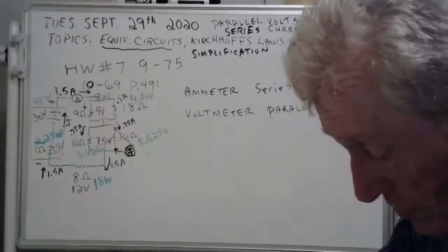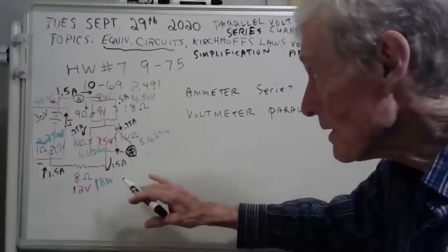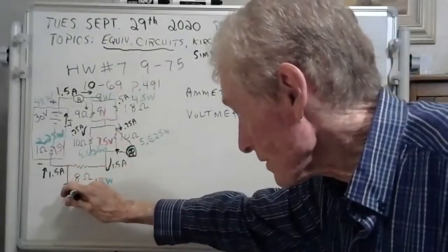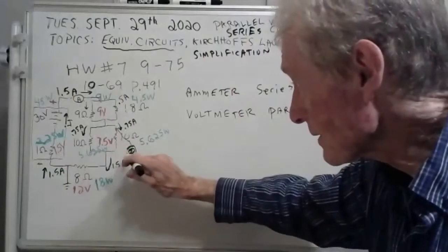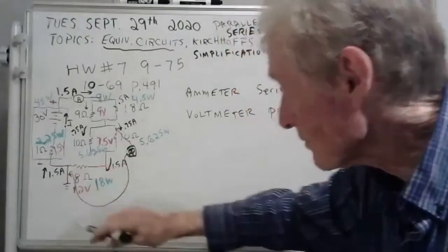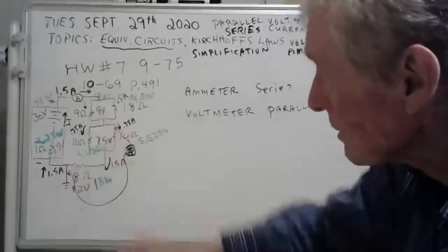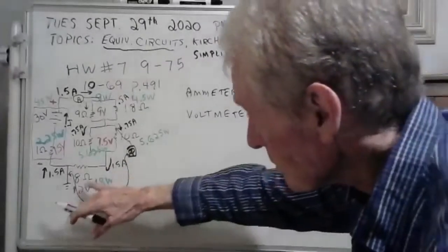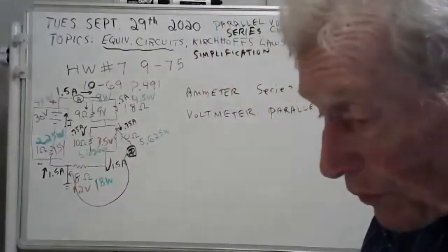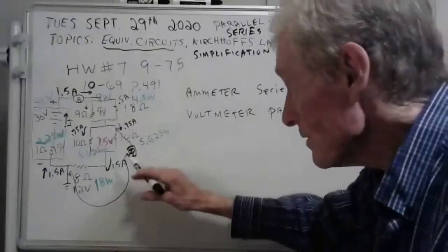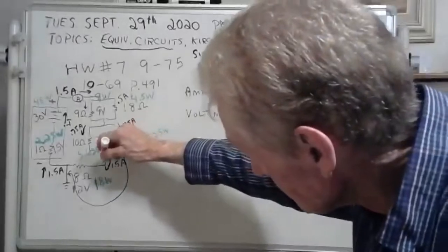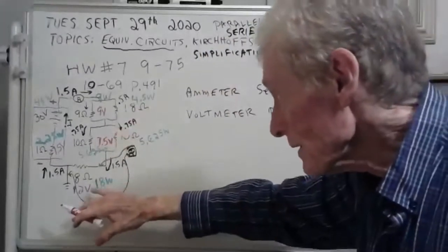So actually, when people are using voltmeters, these things usually have what is known as a ground. The symbol for it is a thing like this. They'll put the black lead right there on the ground, and then they'll measure what the volts are everywhere. And here's what you would get. If your voltmeter is on this ground, that's what we're going to call 0 volts. And then if you connected your red lead to here, it would read 12 volts.